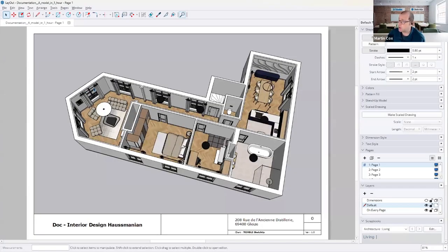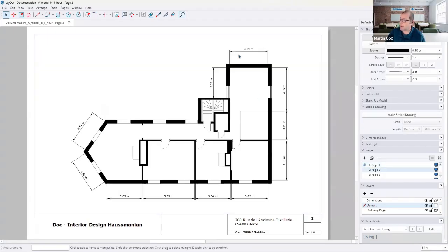And we can import the scene views within layout. So we have a number of pages, and this has been preset. You need to add these drawings, but these are actually links to our 3D model. So if I make changes within our 3D model, they will be changes within our views. We have those different views that we've spoken about. So we have our view here, and this one's been dimensioned. And if I just select my dimensions, I can then say, well, actually, I'd like internal dimensions within that wall as well. If I just double click, it will actually place another dimension for me, similar to the push-pull there as well.